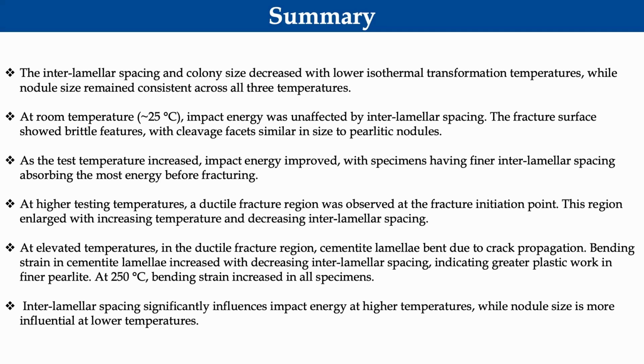So coming to the summary part, we can make 3-4 important points. One, the nodule size remained constant, and we saw the change in interlamellar spacing and colony size. The nodule size was constant because we were austenitizing at the same temperature and for the same time. And at room temperature, we saw the impact energy was unaffected by interlamellar spacing or temperature, because it was only governed by the nodule size.